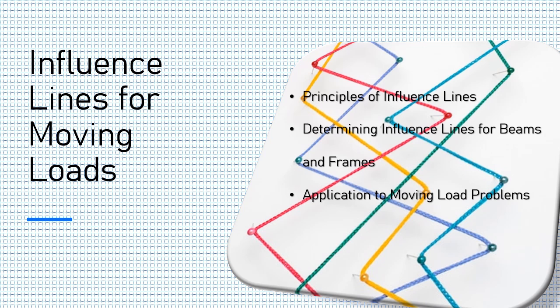8.3. How influence lines are developed. The procedure for developing an influence line for a particular internal force generally follows these steps. 1. Choose a location for the internal force. First, identify the point where you wish to evaluate the internal force, e.g., a bending moment at midspan or a shear force at a particular point on the beam.